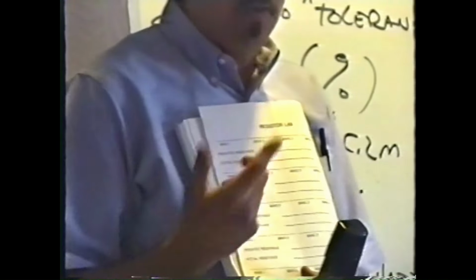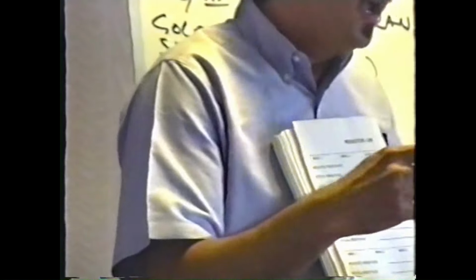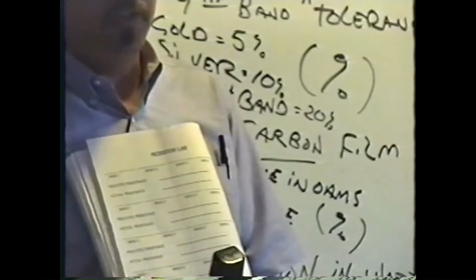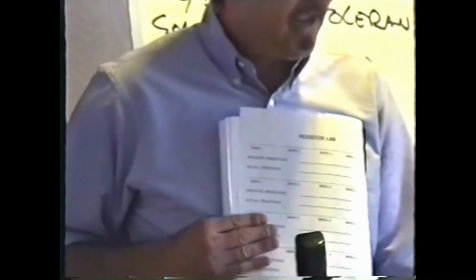I want you to look at your resistor, try to figure out what color it is. If you cannot figure out what color it is, as I often have trouble doing, sometimes you may have to simply measure the resistor, get an idea of what the value should be, and that'll tell you what the colors probably are. If not, ask Shirley or Susan, right? Yeah. What the colors are, because for sure they'll be able to tell us where we probably can't figure it out.